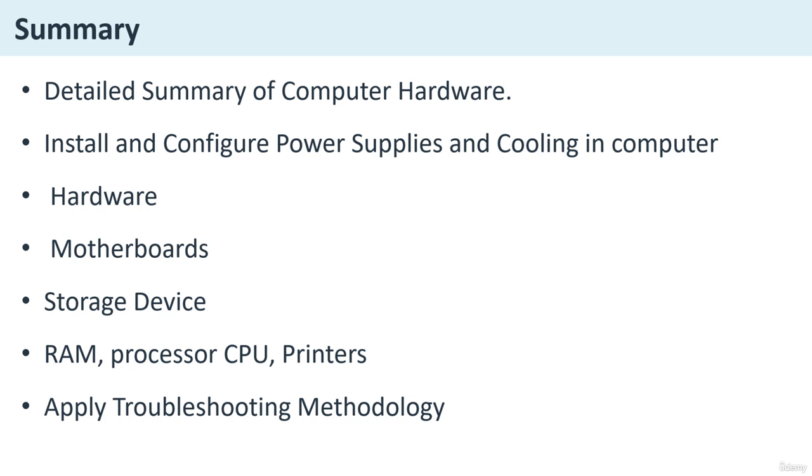Now, another topic is power supply fan types. It is important. 120 mm fan is common, a good balance for airflow and noise. 140 mm fan is larger, wider, but found in higher end PSUs. Now, the third one is fanless PSU, with passive cooling, like no fan, but limited to low wattage builds.